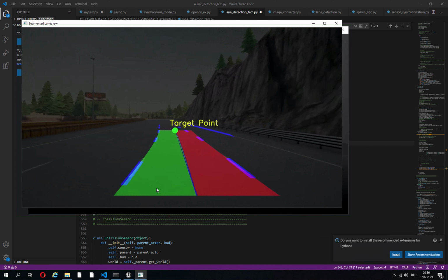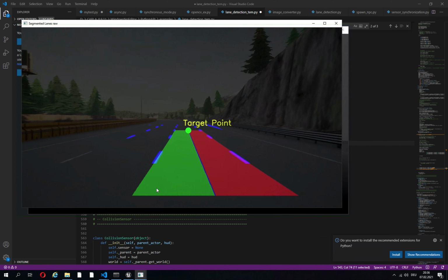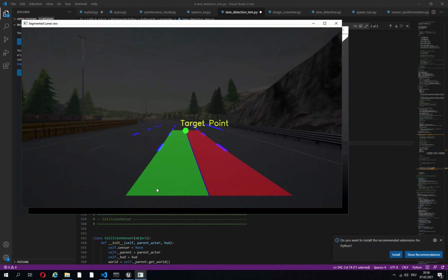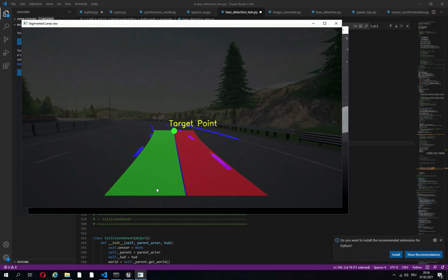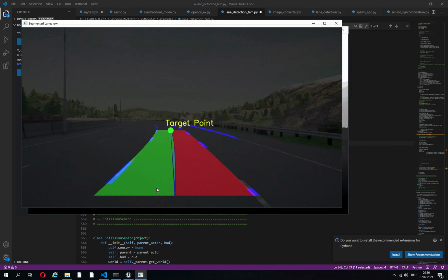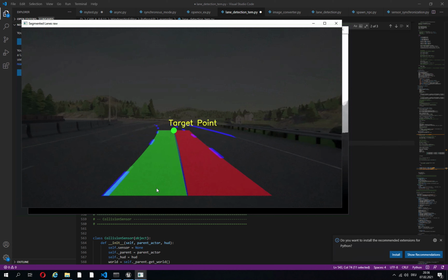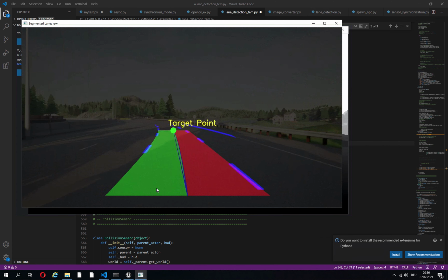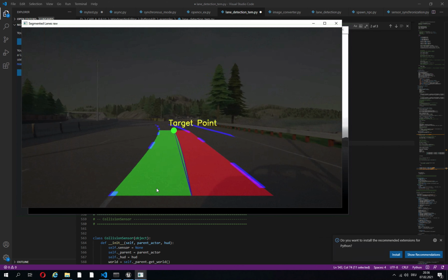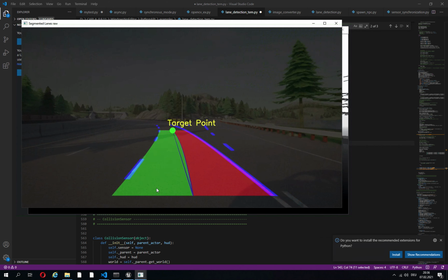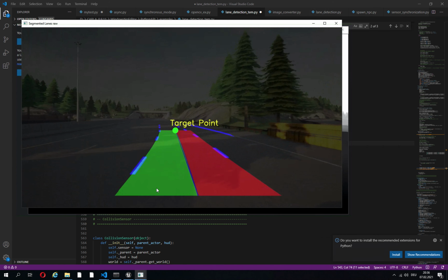In general, what we have learned is, using Unreal Game Engine, we started by understanding control theory, how to do longitudinal and lateral controls: what the pure pursuit controller is, what the PID controller is, and what the Stanley controller is, and how we can use Unreal Game Engine to implement these controllers.